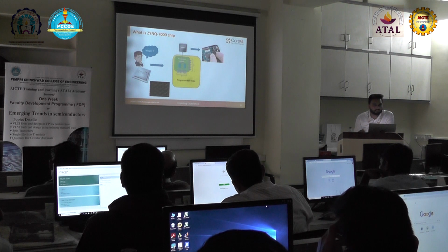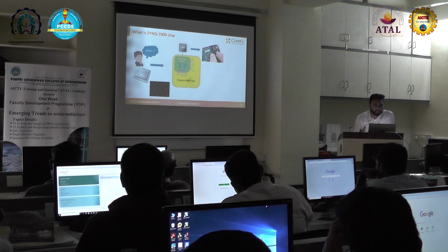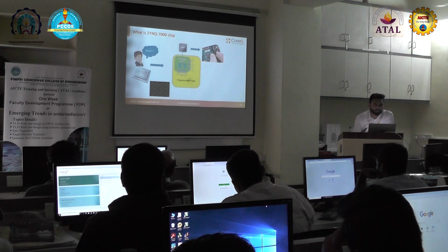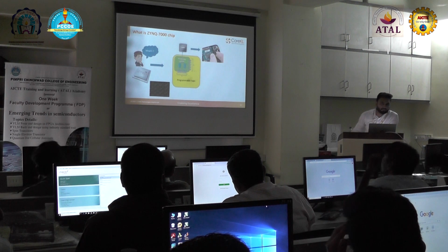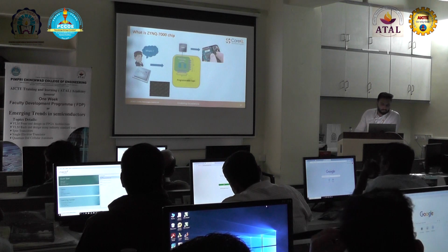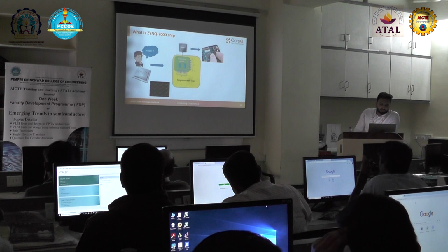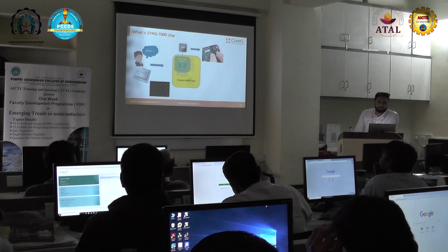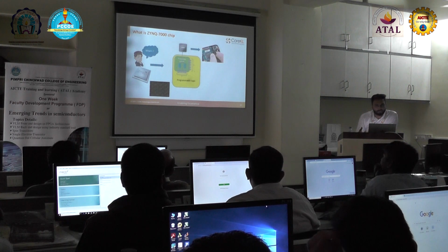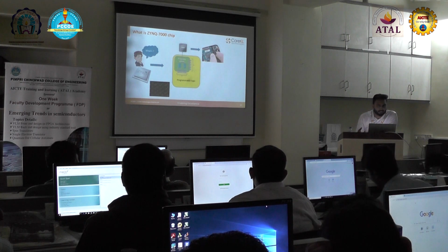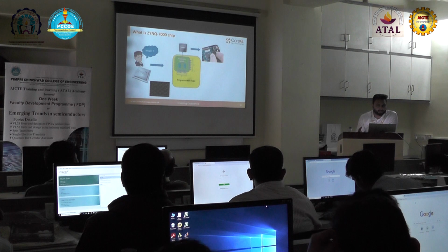These 4 processors come under UltraScale Plus, meaning Zynq MPSoC, multi-processor system on chip. There they are using both ARM Cortex A series and ARM Cortex R series, because you use real-time applications in the UltraScale Plus, and A53 will be used in the APU, application processing unit.